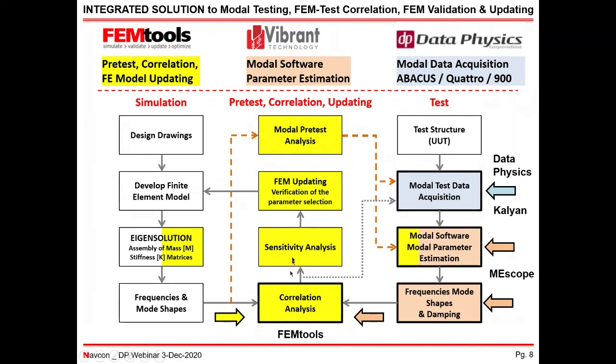And I'm going to show you that here in a little bit. But the other thing I would just say is that we should also look at this other path that, hey, maybe you didn't do something right in the modal test. You should always go back and look at your modal test results. Maybe you need to go through the parameter estimation process again. Maybe you need to redo the modal test.